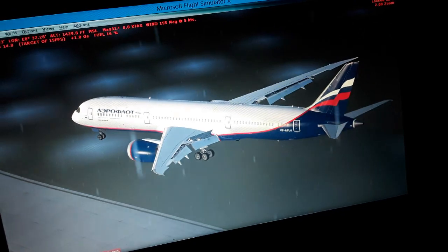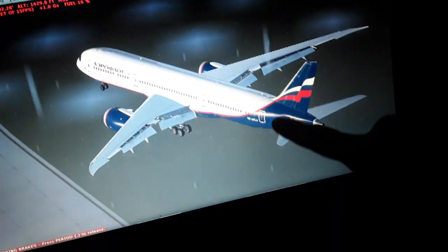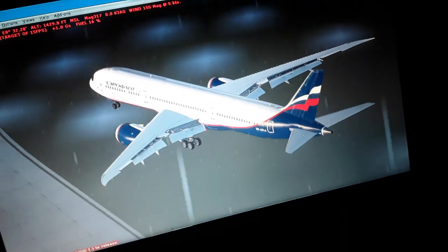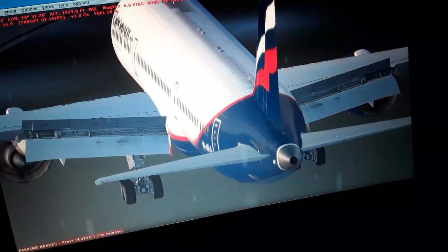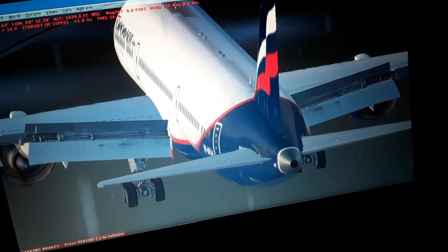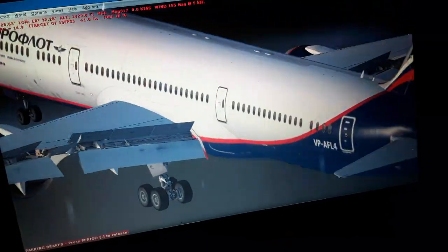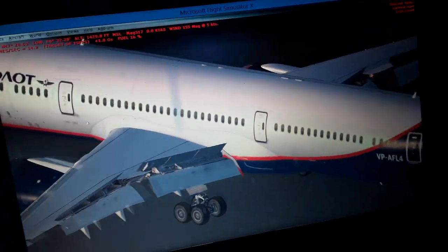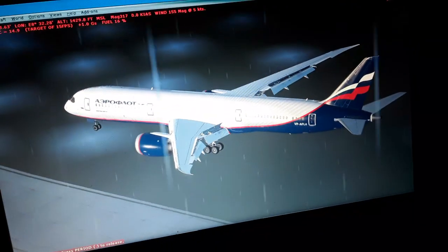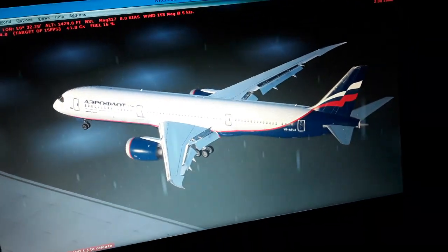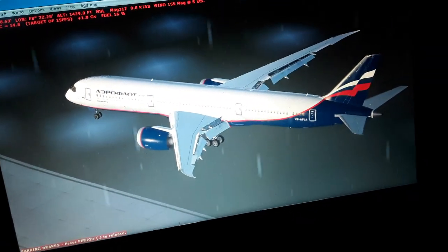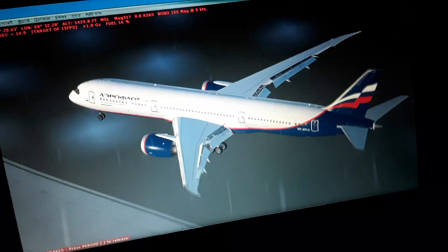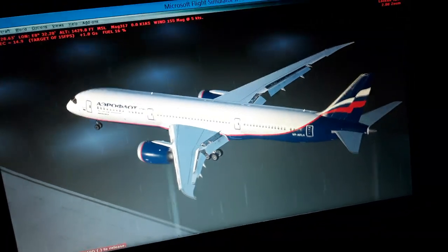You can see the horizontal tail located over here. It balances the aircraft in flight. So we use the pitch trim all the time on the horizontal tail. We use it to climb and descend the elevator, and also trim it to a position to help us balance the aircraft in flight. So I'm gonna talk to you about the forces, Newton's physics, and aerospace engineering factors also used for flying the aircraft.